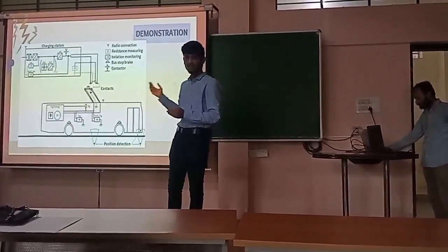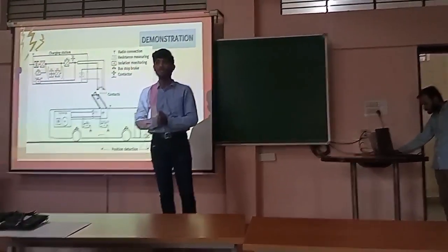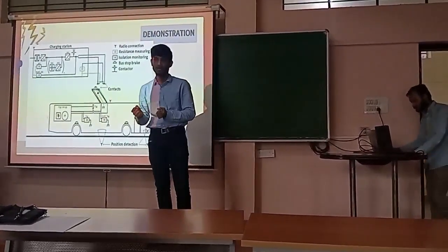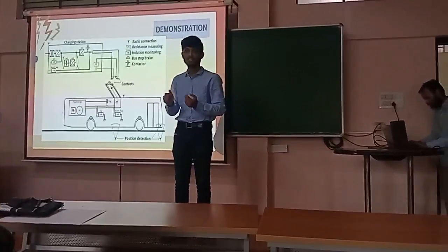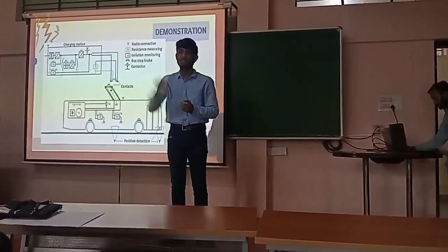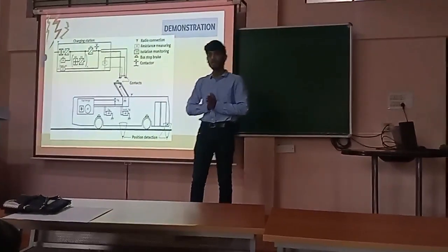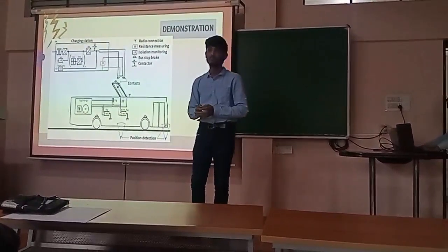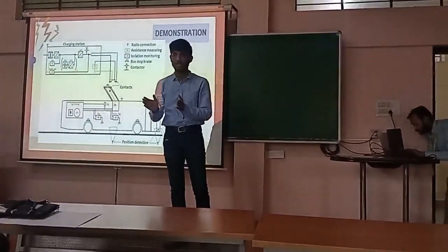So here we are only using ultra capacitors, which have a high capability to charge and discharge. They can easily take on high amounts of charge at once, and they can sustain the charge up to the next coming bus stop. Yes sir, we are replacing the batteries. We are not using lithium-ion batteries.